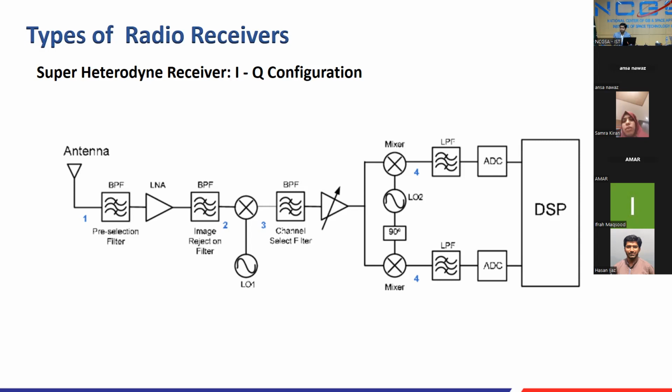That receiver is actually also a heterodyne architecture where you have a first mixing stage. The first phenomenon is the same, it just translates the frequencies. Then you have two mixers, 90 degrees apart. That configuration is known as a Hartley mixer. So that is the hardware implementation in modern receivers.